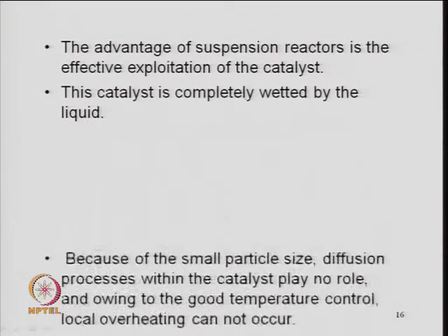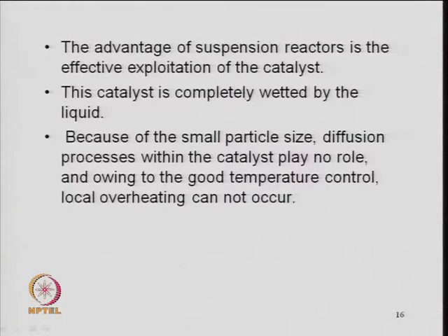The advantage, if you look at what I discussed, is that the particles are smaller in size, right. So, the diffusion process within the catalyst will not play any role, because you have the Thiele modulus, which is based on the particle size, right. So, the effectiveness factor in this case will approach 1. That is one advantage, that the diffusion issues are minimized. So, you will have the complete rate or highest rate in this kind of reactor, right.